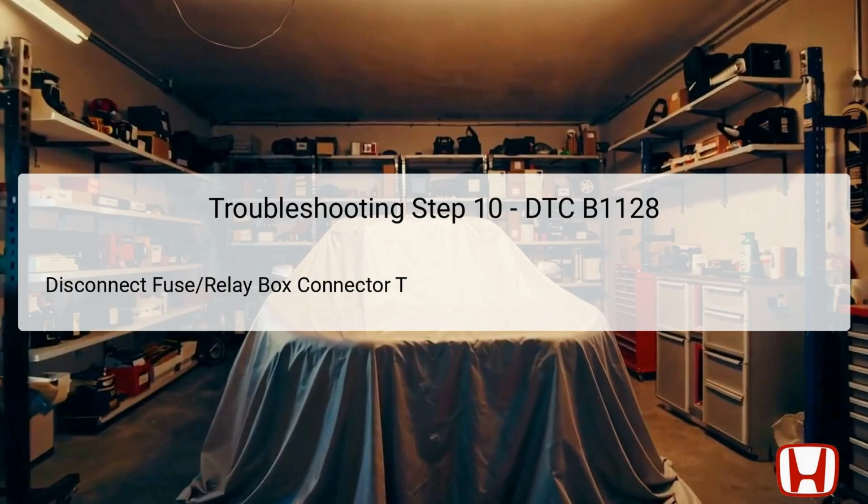Moving to the 10th step, you will disconnect the under-dash fuse relay box connector T34P. This action helps in isolating the electrical circuit related to the locking mechanism. By disconnecting this connector, you can prepare to check for continuity and identify potential shorts affecting the system. It is essential that this step is done carefully to avoid damaging any wiring or connectors.